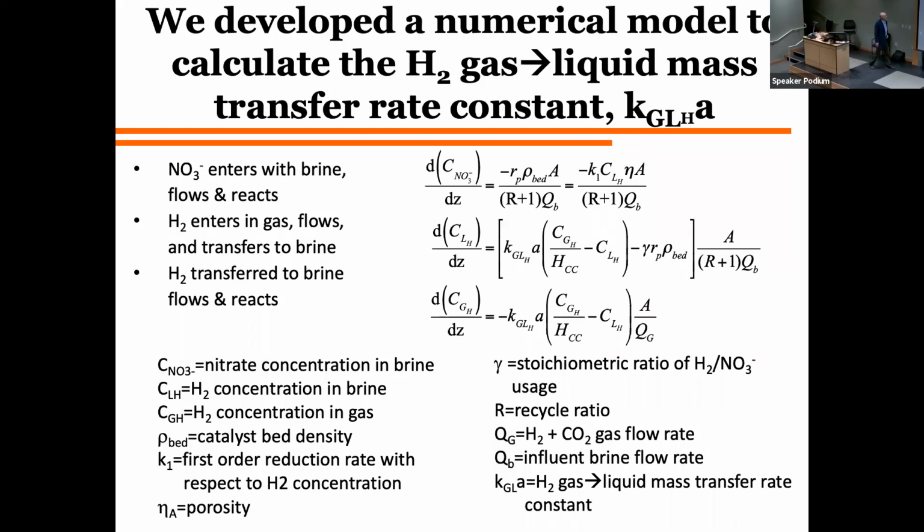So one thing we decided to do was just try to understand what was going on in our system. So we developed a little model, and basically we account for nitrate flowing through the reactor and reacting as it moves through the liquid phase. It's reacting with hydrogen, and we have hydrogen both in the liquid and the gas phase. It transfers between the gas and the liquid phase back and forth, and so you have a mass transfer rate constant, this Ka, and then the hydrogen reacts in that liquid phase. And so basically we wanted to quantify this mass transfer rate constant so that we could see how it affects the reactivity when we have different reaction rate constants, K1. And so we fit this to the data, and then we extended it to the case for different reaction rate constants of the catalyst.